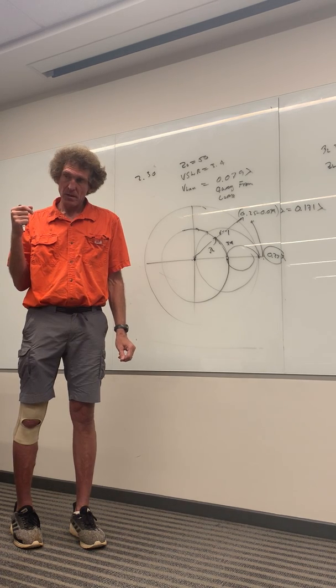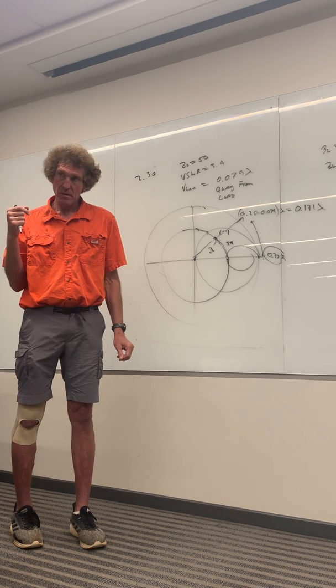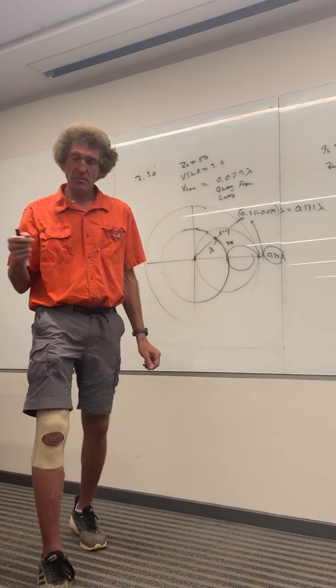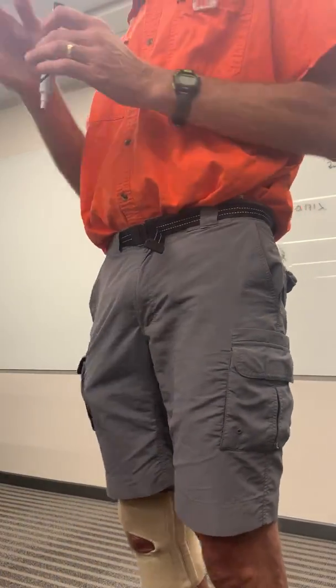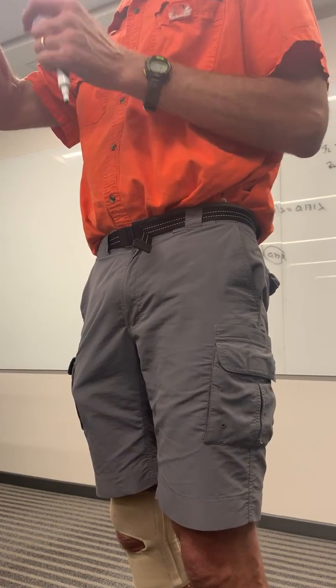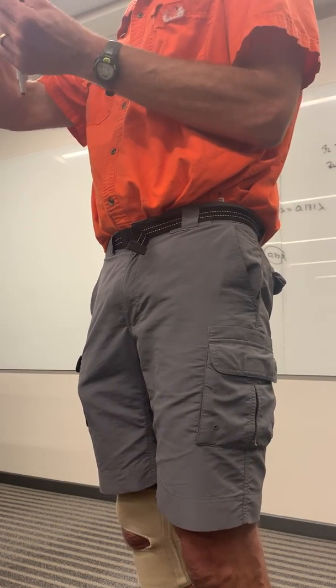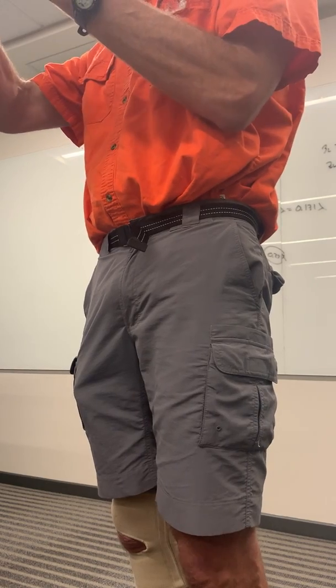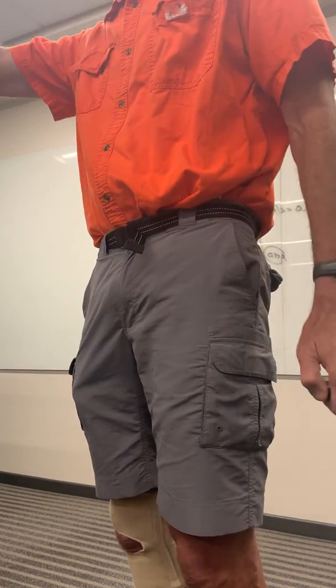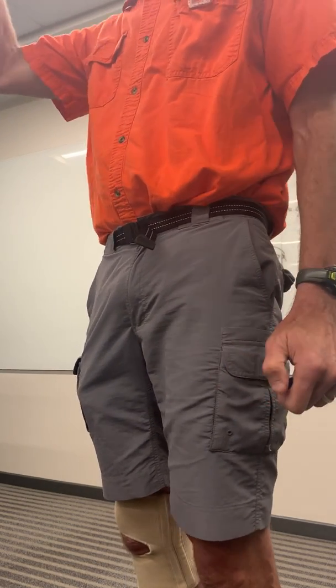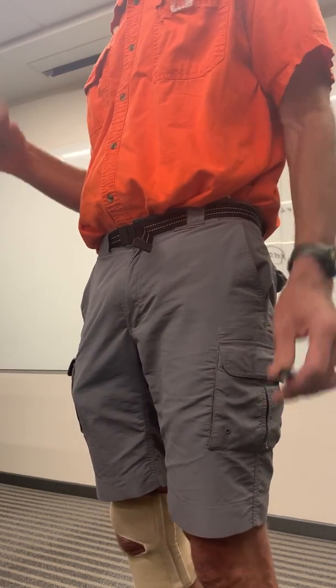Oh, like the coaxial cables and whatnot. This is probably measuring Vmax on a coax. There's a thing called a slotted line that they use, and you can actually take a look at the voltage between the inner core and the outer shield on a coax with this little thing that you move up and down. It's got to be a split line to do this though, but it's an experiment more than anything.